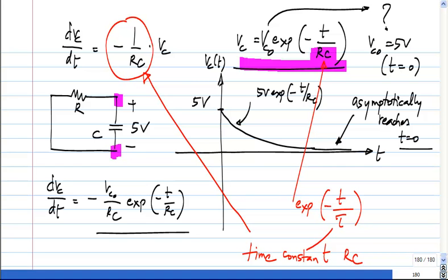Okay. So, it influences the rate at which this falls. What happens if this time constant is very large? What happens to this curve? Will it fall quickly or slowly? Slowly, right? So, because if let us say R is very large, I mean the time constant could be very large by the R being very large or C being very large. If R is very large, what it means is that the current is very small. Okay, initially for the same 5 volts, the current is much smaller. So, that means that it will discharge the capacitor lesser. After all, what is happening? Initially, you have some charge across the capacitor that is leaking through this R, and then goes all the way to 0. Now, if the resistance is very large, then it means that very little charge is taken out per unit time. So, it discharges very slowly.